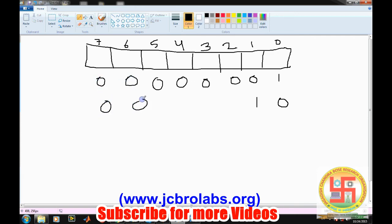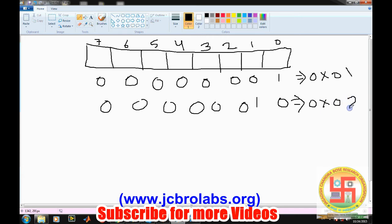So we can say all other values are 0, 0. So its hexadecimal code is 0x01 and the other is 0x02. So we will simply supply 0x01 to port 1 and 0x02 to port 2, and then the motor will run in one direction, and then after some time the motor will run in another direction.